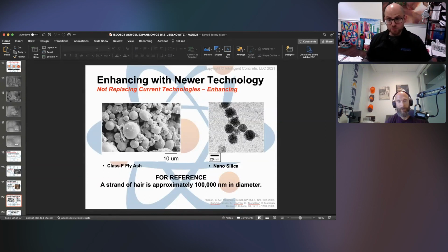Normally, you have to put something in there to break the oil down, like an acid, like vinegar or lemon juice. When you don't do that, the oil pulls to the surface and you have the water below it. What silica will do, if it's not suspended, if it's not in colloidal form, is cake up and agglomerate together, then fall out of solution and stick to the bottom. Okay. So where oil will go to the top, silica will go to the bottom. Colloidal means that you're not going to have that caking problem on the bottom.